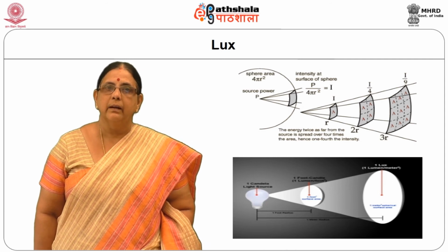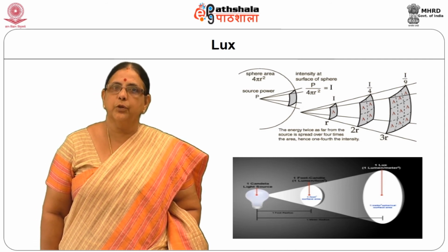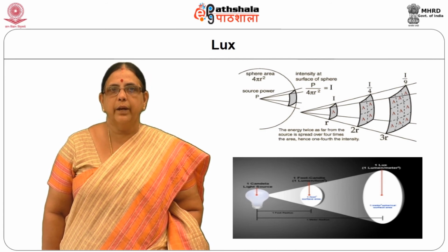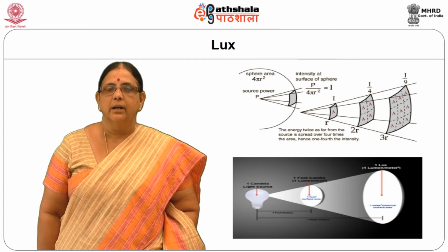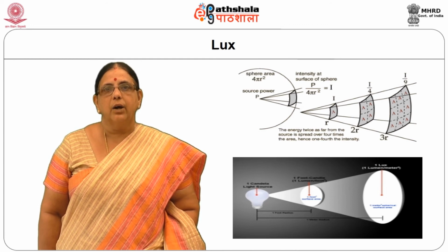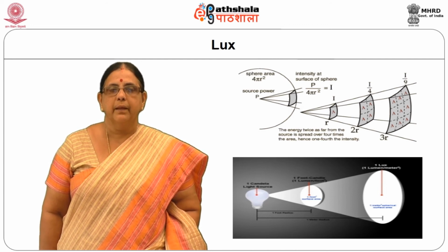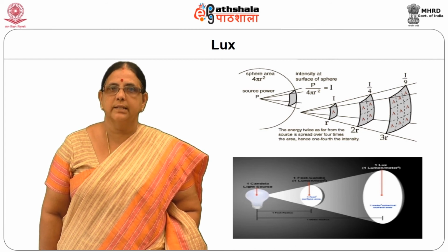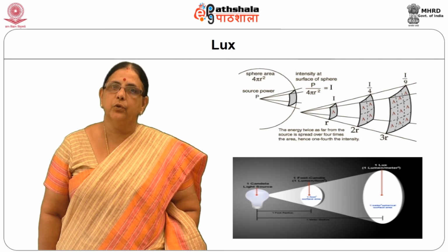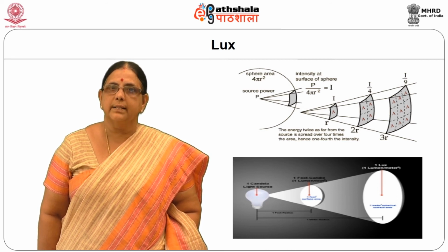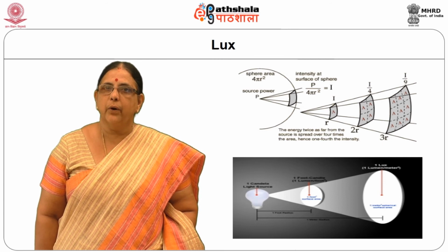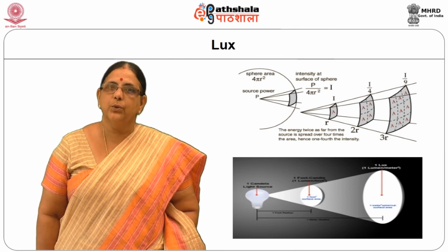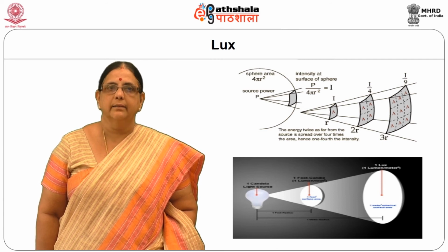Very good. Lux is used in photometry as a measure of the intensity, after analyzing the way the human eye perceives it, of light that strikes or traverses through a surface. It measures the incident light available at a known distance. It is a metric unit of foot candle. 1 lux is equal to 0.0929 foot candles. So, it is used to be called as a meter candle.